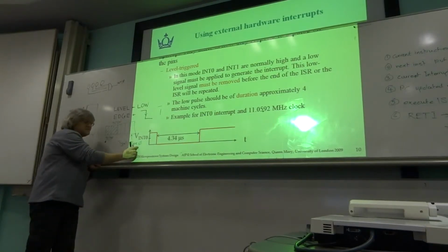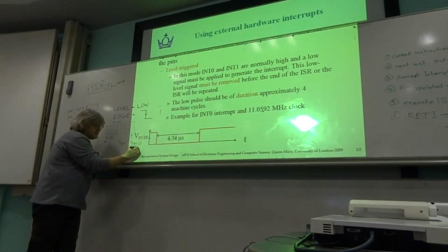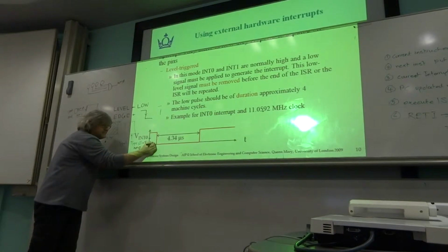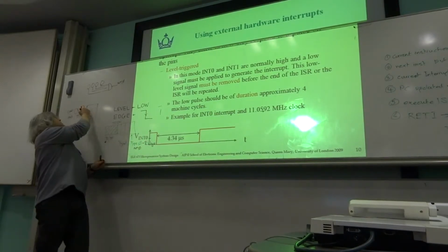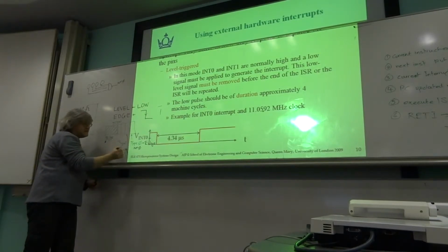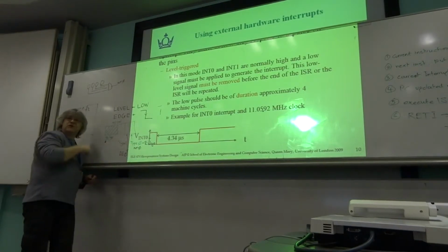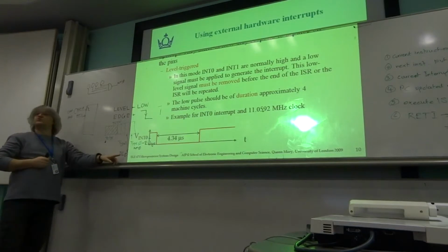So if you've chosen for this interrupt 0, you said, I want this to be edge-triggered. When that goes from a high to low, another bit in this register will go high, which will be the IE flag, I think it's called, which is interrupt edge, associated with that interrupt. It will go high to tell you that the edge has happened. And that will trigger the interrupt.